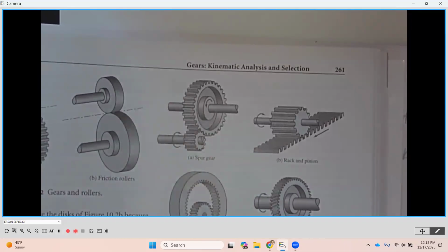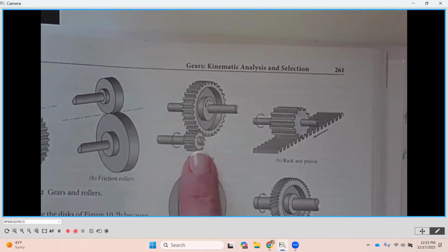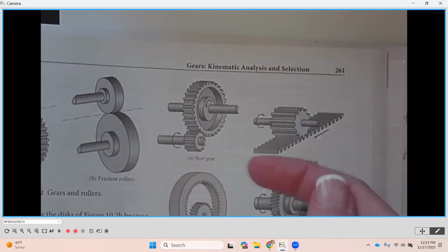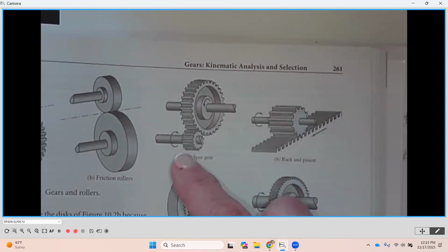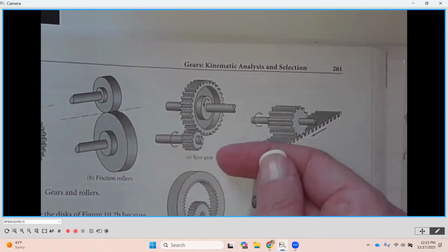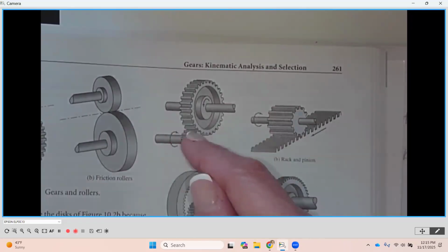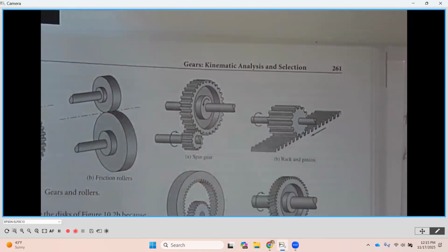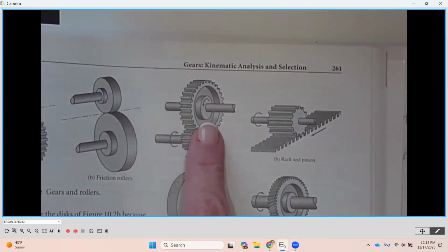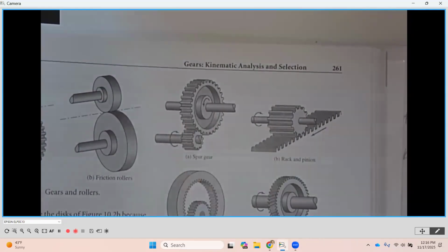We're also going to notice that when we engage one gear to another, we're going to change the direction of rotation. So if we look, in this direction, for the orientation of these gears, if my driver is going in a clockwise direction, looking down the center line here, this would be clockwise. Notice that it changes the direction in an opposite direction, and it would be counterclockwise then for the mating gear. That's something to take into consideration as you design the final function of the gear set.